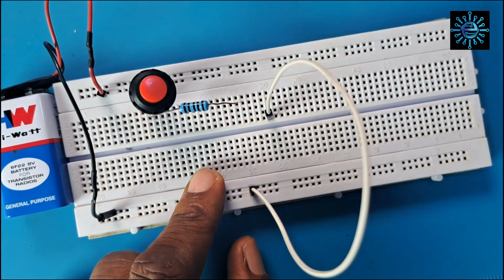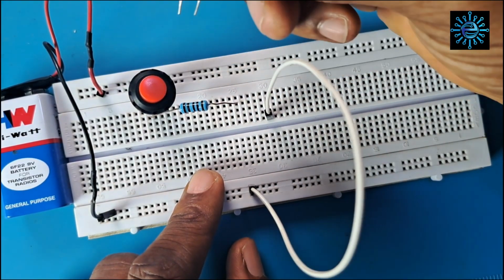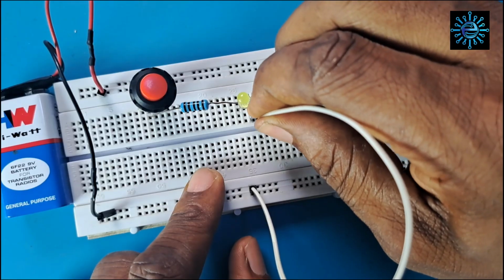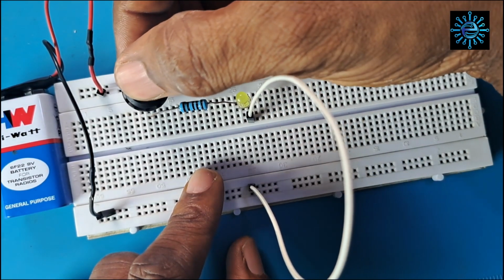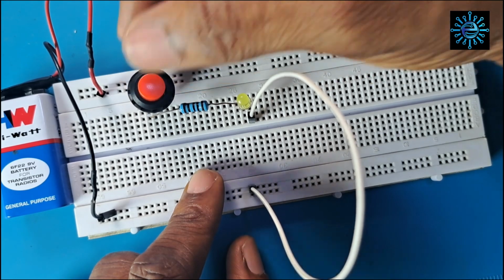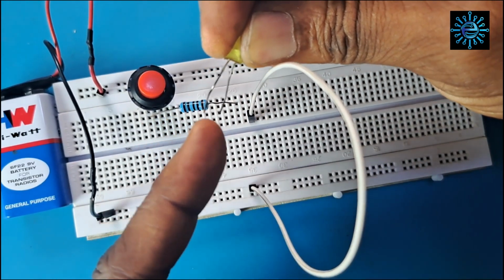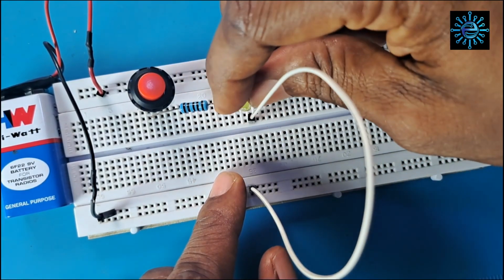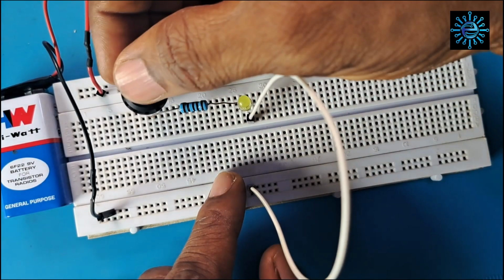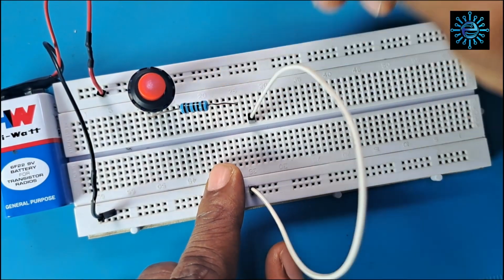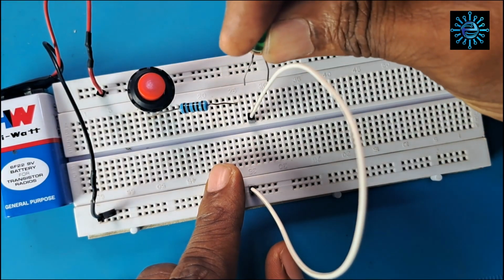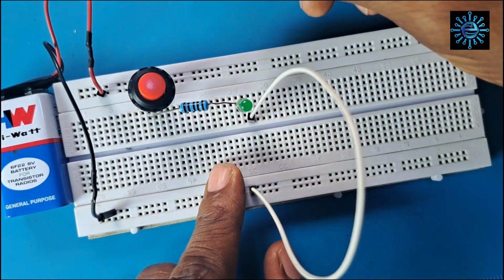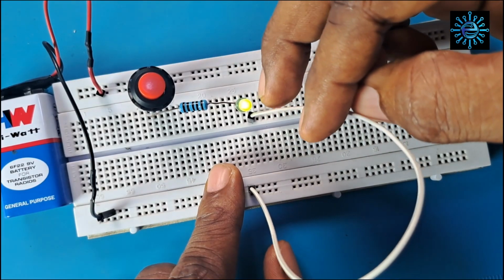For example, here I have a faulty LED. Let me connect it in the circuit the appropriate way. So I will connect this LED and I will connect the jumper wire. When I press the switch, the LED did not come on, though I connected it the right way. This is the positive leg and this is the negative leg, and I connected it in the circuit, and you can see that the LED is faulty. So to solve this problem, what I will do is I will change to another LED. So I will replace that LED with another one, and if I do the replacement with a good LED and I press my switch, you can see that the LED is on.